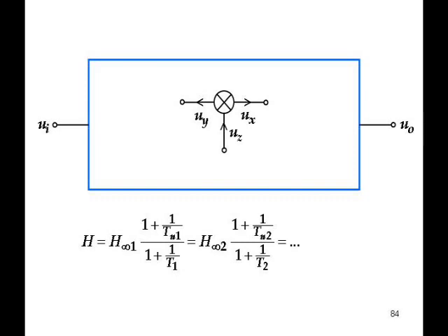Doesn't have to be a loop necessarily. You can choose any injection point you want, and you get different sets of second level transfer functions, all of which give the same H. So I just labeled them randomly, sub 1 and sub 2, sub whatever number you like. All different, but all give you the same answer, whether there's feedback or not.